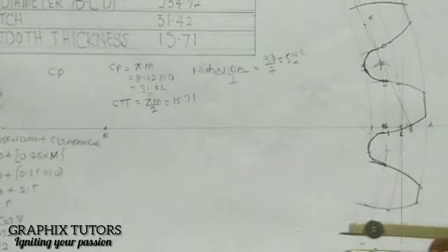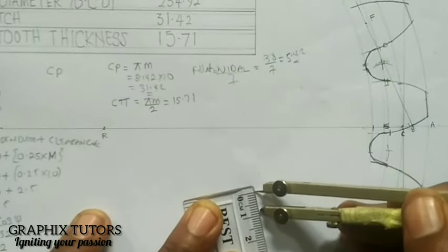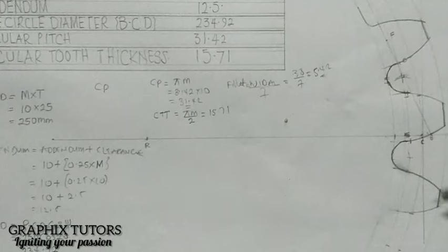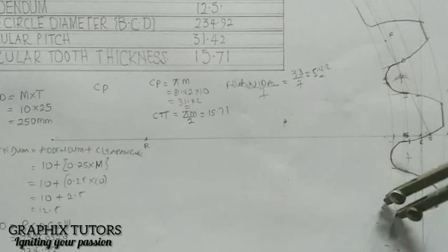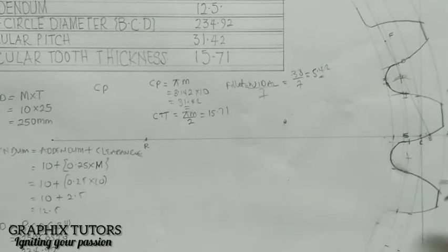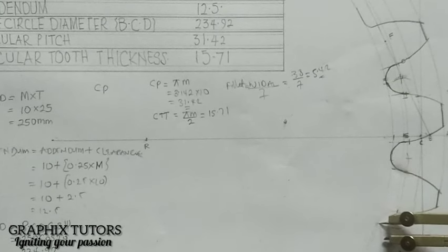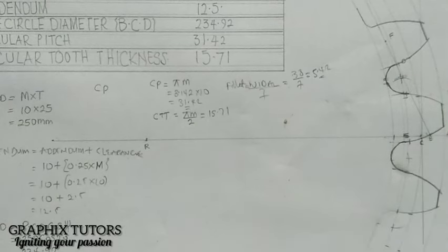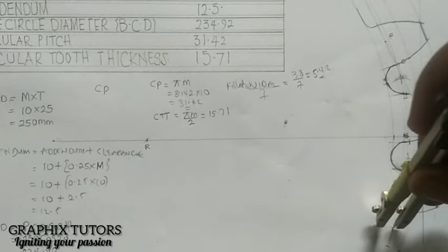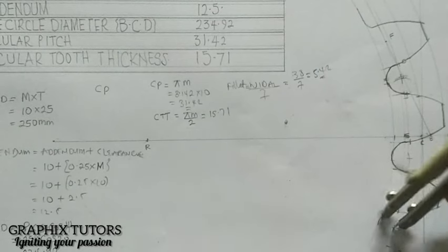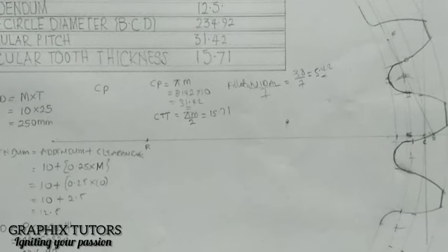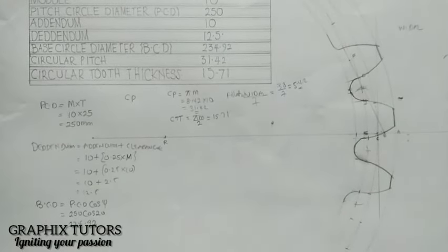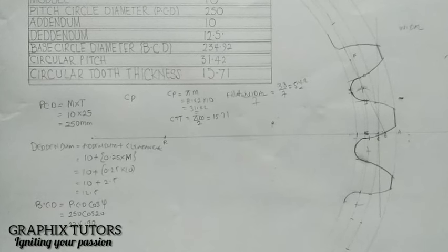You come here to the same 5.42 that you measured earlier, which is still the same thing. Place it here where they meet, and you mark on this, and you mark here, just like you've been doing. And you place it with the same radius. You strike an arc, same radius here, strike an arc. So where they cut, you use your compass and you join. Right? So this is a gear of size 3, right? I will call it a Spur Gear, right?